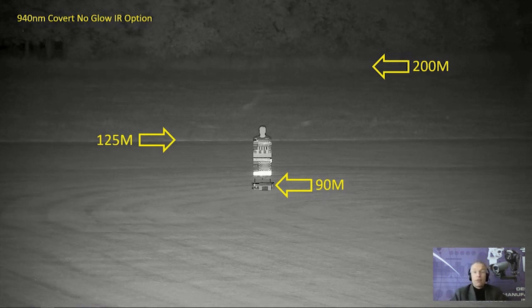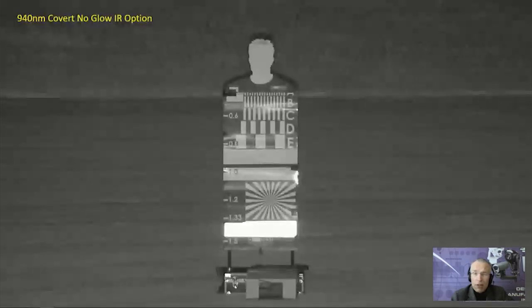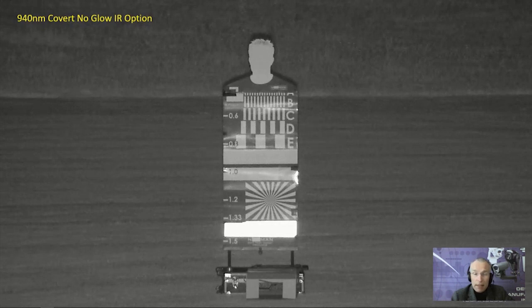So our radar essentially tracked out of that distance, and we could provide illumination. In actual fact, more impressively with this particular image, this is using IR illumination at night, which is our no glow illumination. So that's 940 nanometers. So it's so far up the range as far as IR illumination on CCTV is concerned.